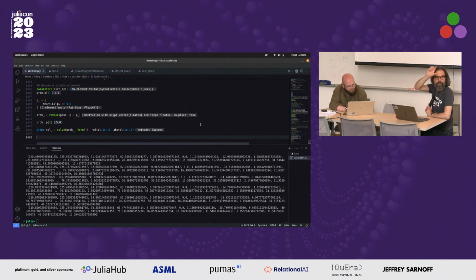Then you define P map as square brackets, name of the first parameter, right arrow mapping operator, P1, P of 1, the name of the second parameter, mapping operator, P2, the name of the third parameter, mapping operator, P3, and then you hand that into remake problem, P equals P map, and then you run the problem again.